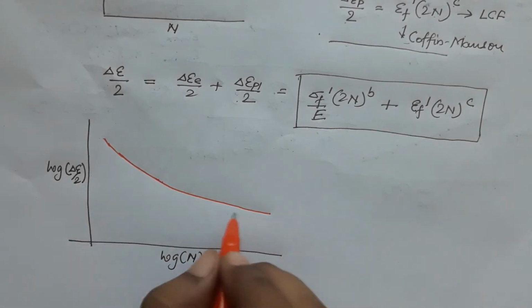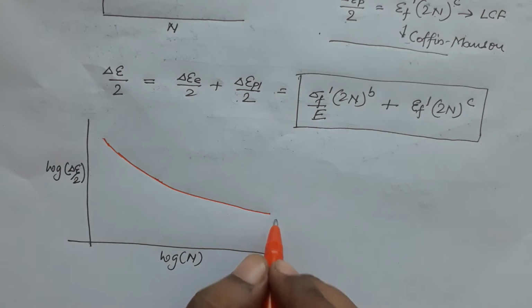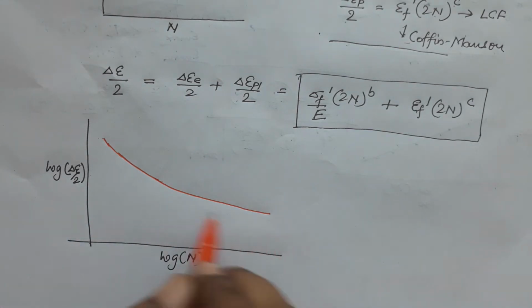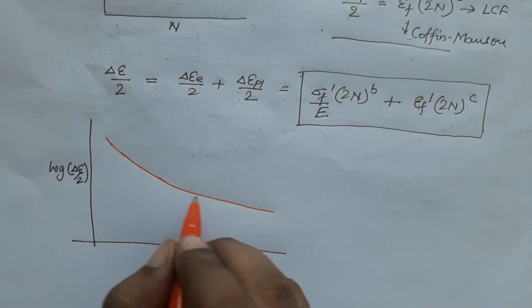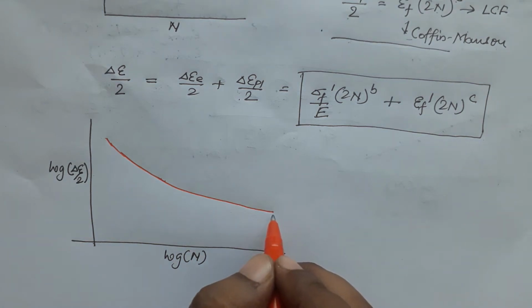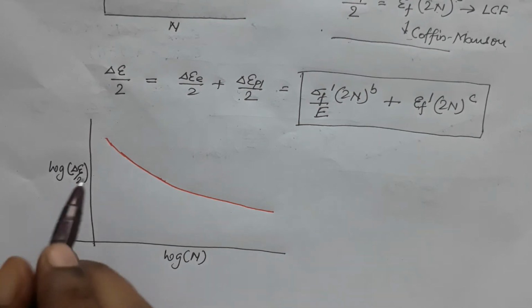Here I am not drawing any line which will show you fatigue limit, because fatigue limit only happens to few materials, especially steel, especially BCC alloys, and for other materials we do not find the endurance limit or a constant line like that. Even for steel, we have discussed this before, that even for those materials for which fatigue limit is defined, it is not true. The fatigue limit actually does not exist even for those kind of material, but you will have to go longer on x axis to see that.